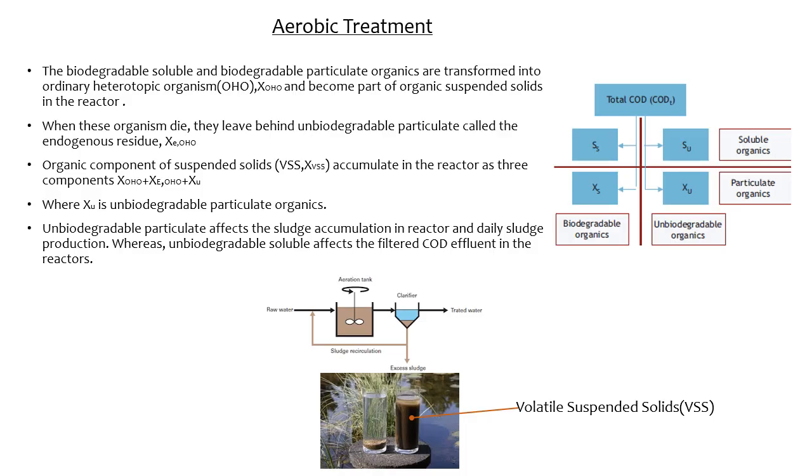In aerobic treatment, the COD fractionation is important to understand the wastewater to be treated. The volatile suspended solids (VSS) or mixed liquor volatile suspended solids (MLVSS) in a reactor of an activated sludge process contain ordinary heterotrophs, which consume biodegradable soluble and biodegradable particulate organics. When these organisms die, they leave behind unbiodegradable particulate called the endogenous residue (XEOHO).